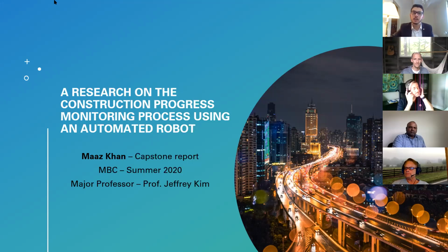Currently, what actual contractors can do is take a drawing sheet, decide where they would want the robot to traverse in that building, put spots down in that drawing sheet as to where they would want pictures taken, and then use a tape of whatever color and mark out that path so that every day that robot can go through that path. But right now, automatic integration of drawing sheets online to the robot is not currently capable.